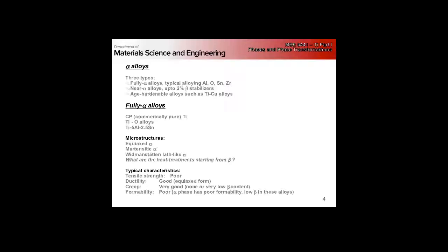So it doesn't matter if you cut out along the rolling direction or orthogonal or 45 degrees, right? Because those prism planes are randomly oriented. But if you were to do compression, say through thickness, you'd have a different response because you're compressing on the C-axis. So depending on what you want, titanium alpha sheet can either be strongly isotropic or strongly anisotropic, right?